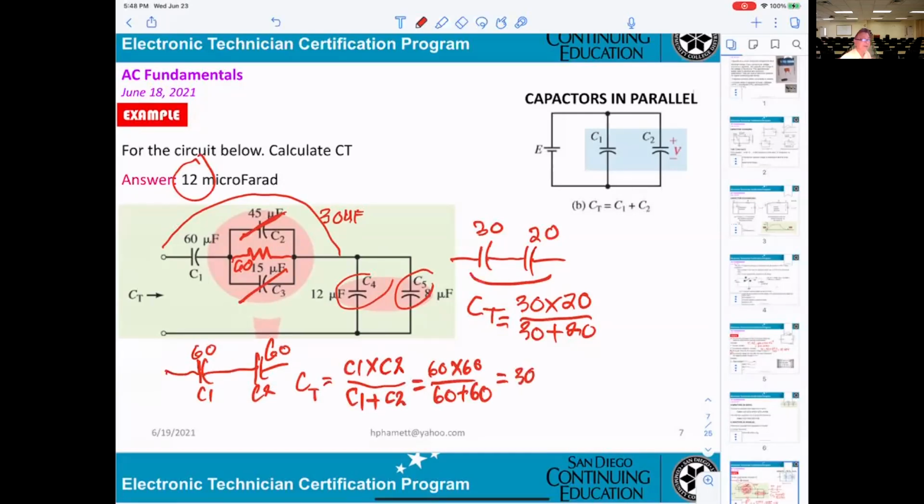However, normally, whenever you get two capacitors in series with the same value, the total will be half of that. You don't have to do the calculation. Like with resistors of the same value in parallel: if you get 50 ohm and 50 ohm, then you know for sure the equivalent will be 25. The same applies to series capacitors.